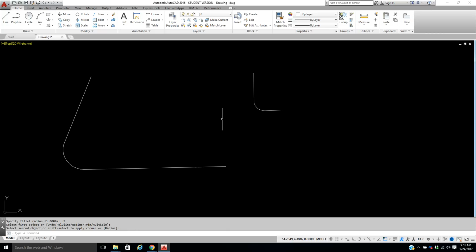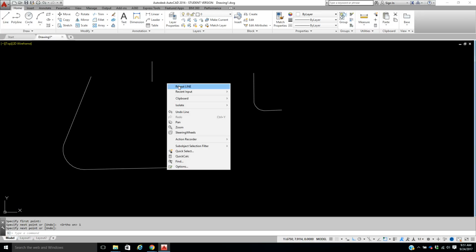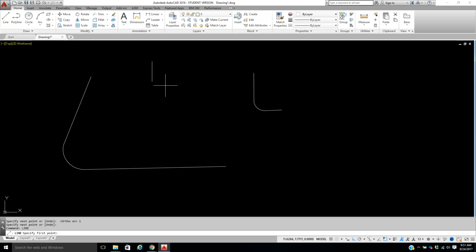The thing you've got to remember is that your line, for example, if I had a line that was only, let's take it here, let's say this was 1 inch, okay? And if I did another line over here, and I said this one was going to be 2 inches. If I go to put a fillet on here, and I did a radius of 2 inches, if I went to pick this and this, it's not going to let me do it.